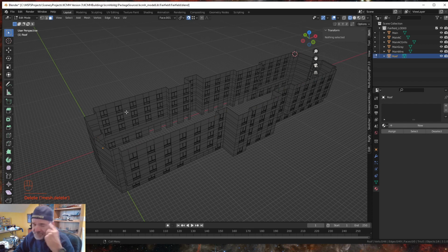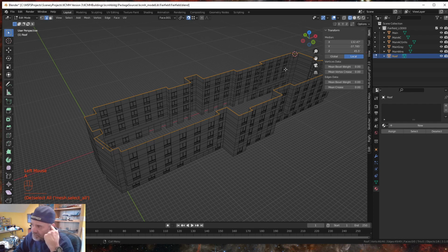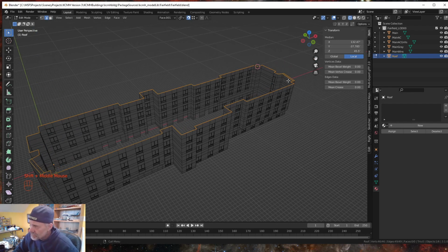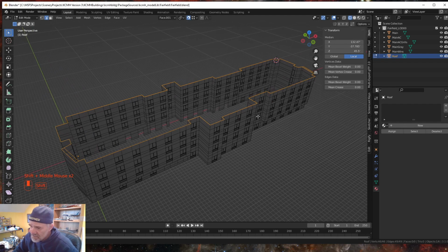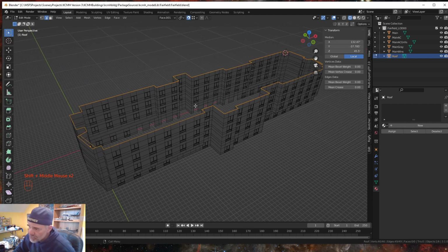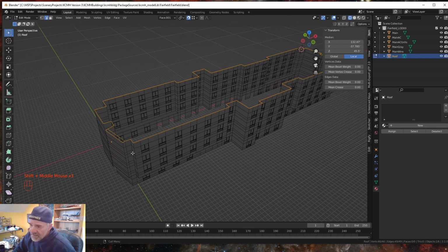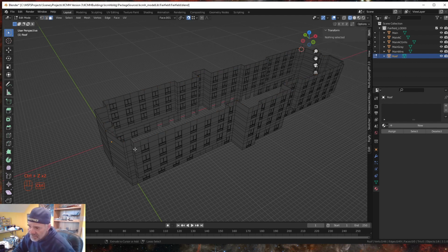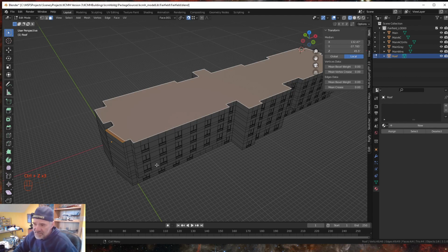All right, now if I go to edge select, select all, notice that I don't have any faces, I just have these edges. But I don't want this edge, and I don't want this small little edge here. I want to combine them into one face. There are 2 different ways to do that. Let's Control Z for a second and bring back our faces that we deleted.